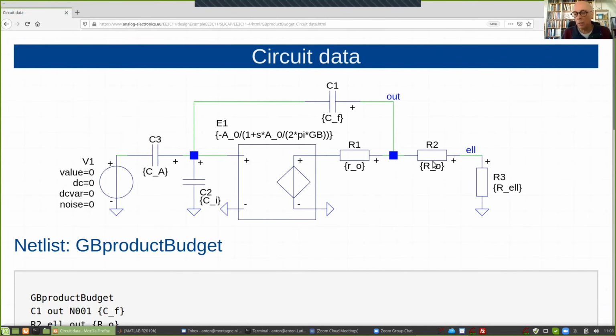We have here 50 ohm and 50 ohm, and here we have something like 3 pF. So 3 pF and 100 ohm. If the output resistance of the operational amplifier were infinite, then the pole, let's say if it is 0, it doesn't create a pole because I have a loop of capacitors and voltage sources if this is 0. So if it is finite and it has the largest possible value, let it be much larger than 100 ohm, then the pole